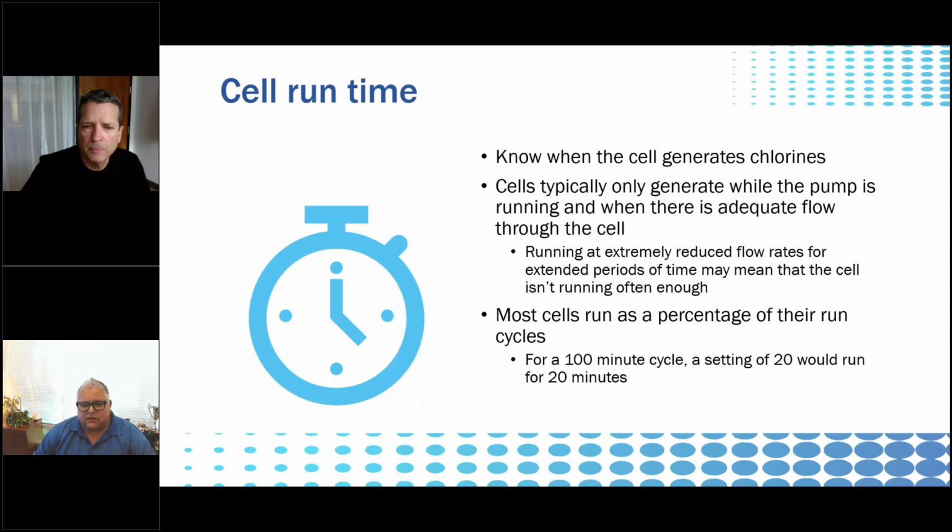The other thing I always want to caution you with is with the popularity of variable speed pumps, a lot of people like to run their variable speed pumps for lots and lots of hours on very low speeds. That's great for energy and terrible for chemistry. So you have to make sure on those variable speed pumps, they're good. I have nothing against variable speed pumps. They are really good and energy efficient, but you can't just leave them on the low setting and say, I run my pump 24 hours a day. You've got to bump them up to the high setting.